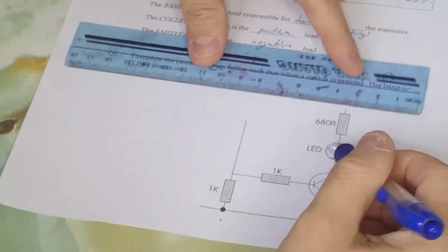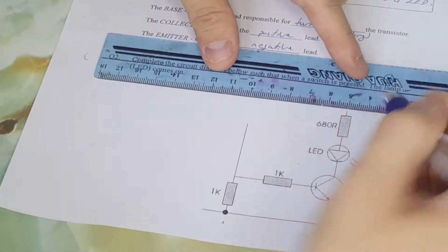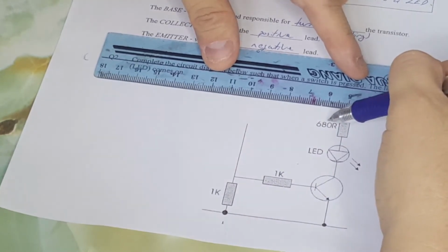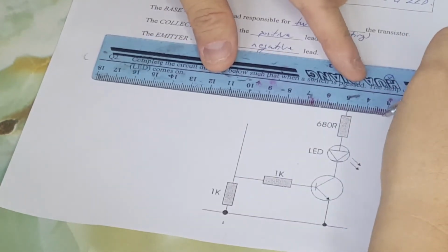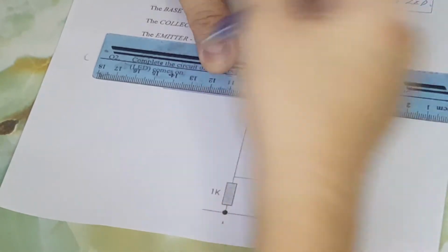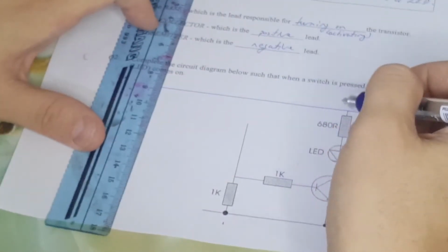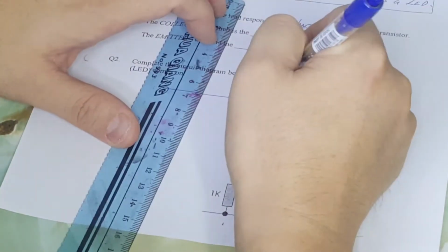Okay, so as you can see, we're going to start completing the circuit here of question 2 of your worksheet. Since this is the highest part, the 680 R here represents a resistor, so this is a 680 ohm resistor. So you just need to draw a horizontal line parallel to the ground line, which is at the bottom. All right, and of course I've actually drawn beyond the line, and it'll be good if you can connect a switch, which is down here.